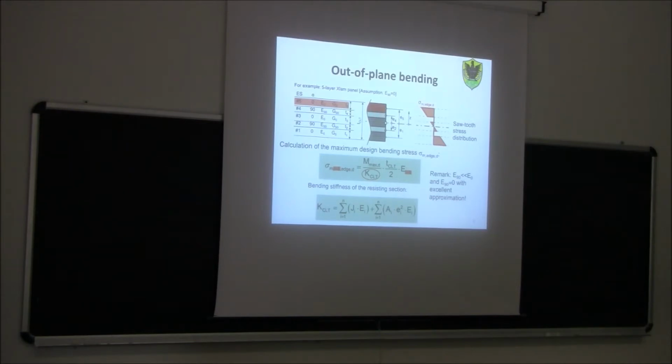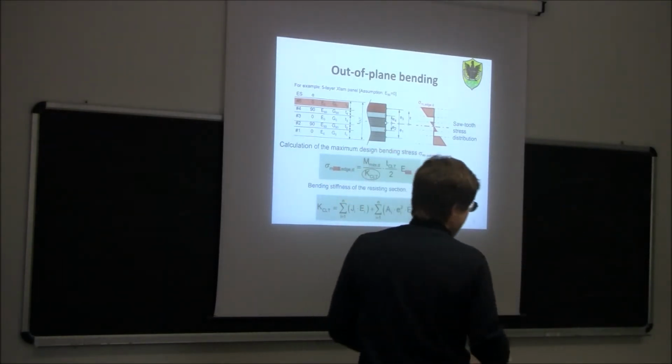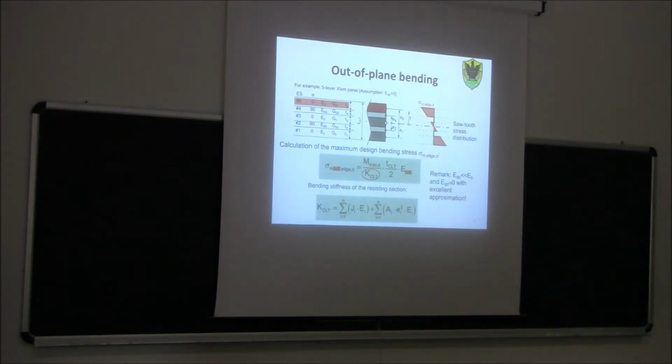You should consider the Young modulus of wood perpendicular to the grain. And then in this case, you would have to homogenize using what we call the transformed section method. But again, since the differences are really negligible, I would say just ignore the intermediate layers, so the ones that